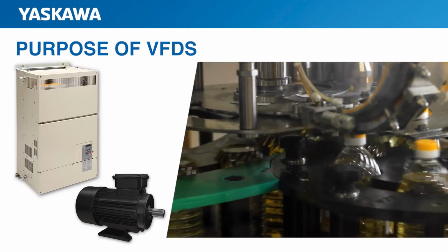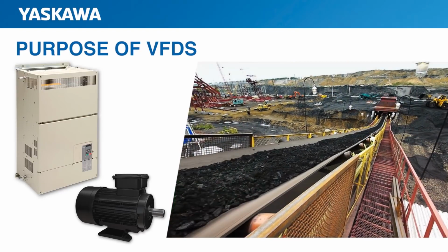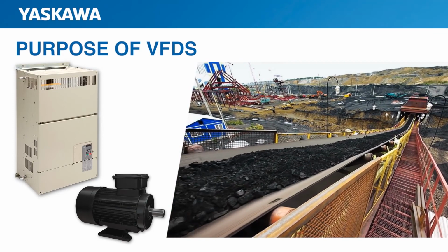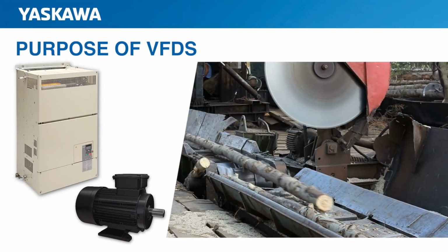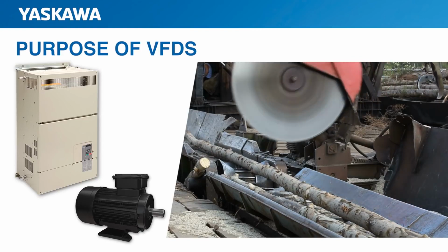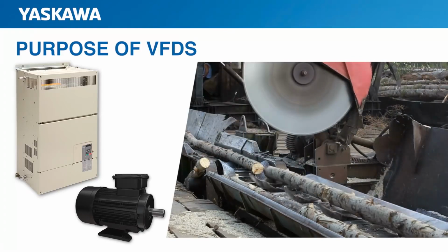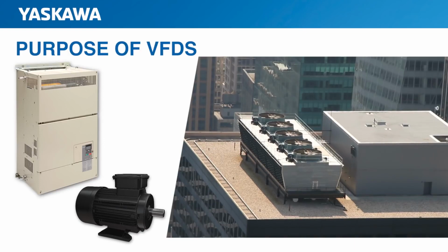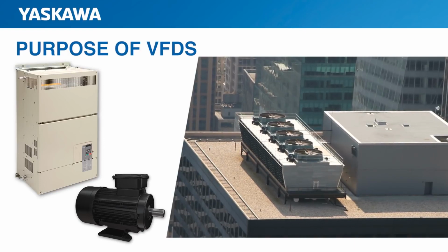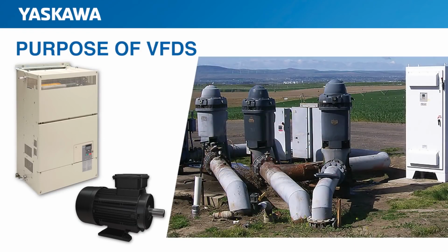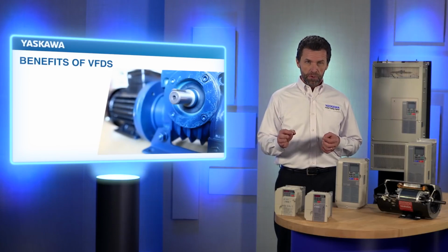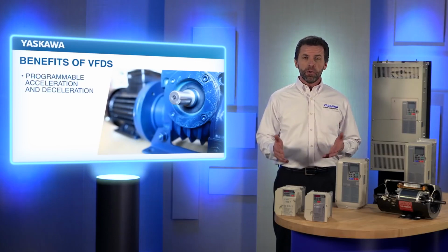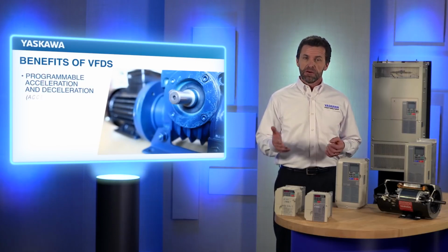Operating a motor with a VFD provides full torque capability over a wide range of frequencies. Having full torque available allows us to use a standard or general-purpose motor in many more applications and situations than we would otherwise be able to. Furthermore, we can limit the output torque of a motor for a given application or point in the process should it be required. Since we now can control the motor, we can program our own acceleration and deceleration, or accel and decel times.